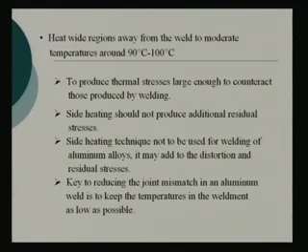It is like this. With higher temperature, the stress level does not directly depend on the temperature level. With a higher temperature level, your residual deformation can be high, but at a lower temperature level it is trying to expand and it cannot expand, so the stress level can be equally high. Stress level can be equally high, but the deformation level will be low with low temperature.